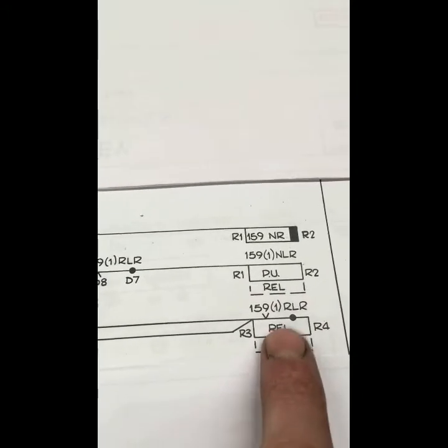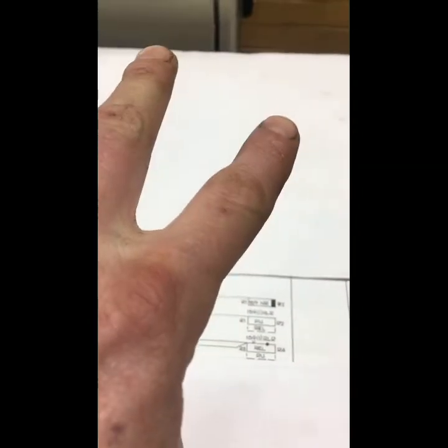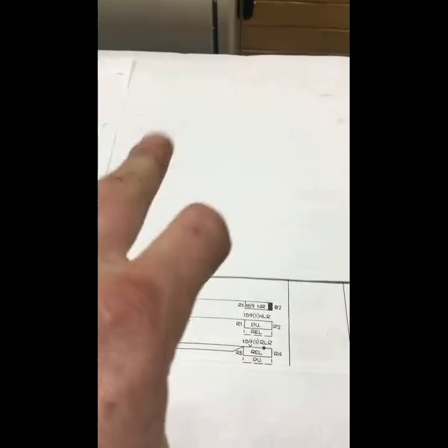So this is currently picked up, and we remove the feed off that. In removing the feed off that, we also need to energise the release side of it. So we will release the RLR, and that will energise. So it's a very quick momentary action, but what you don't want is you don't want both of them dropping at the same time, because one has to pick the other first before it drops out.